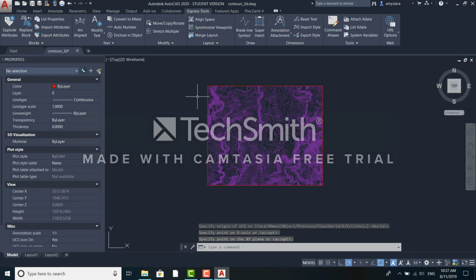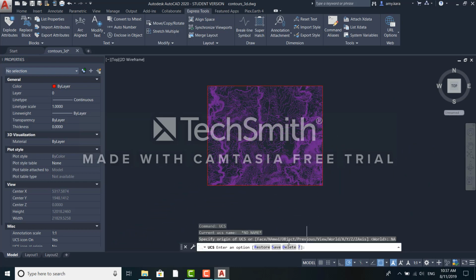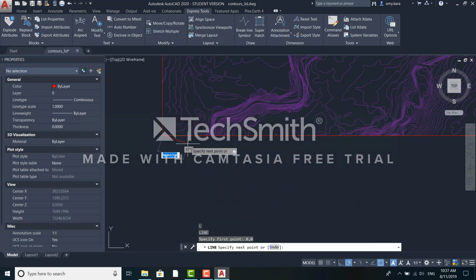And then we're going to type in UCS again, and then we're going to go named, and then we're going to go save, and then we're going to save this as 3ds Max, just so that we know that this UCS is for 3ds Max. And then we can just test this out by going L and specifying 0,0, and it should start drawing a line from the new XY UCS.